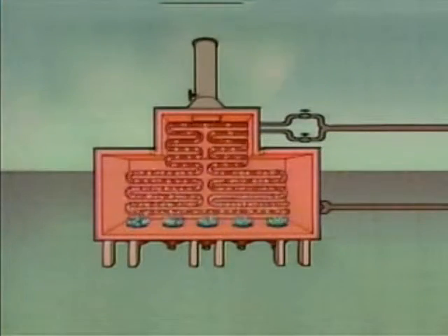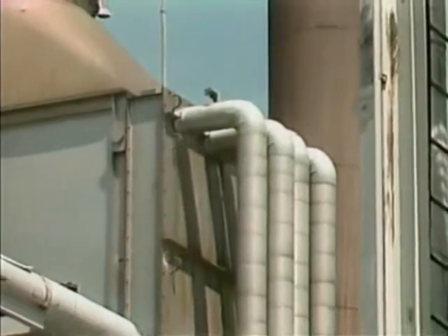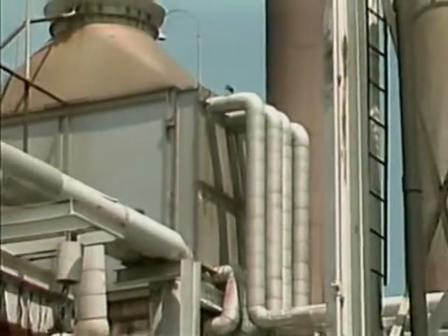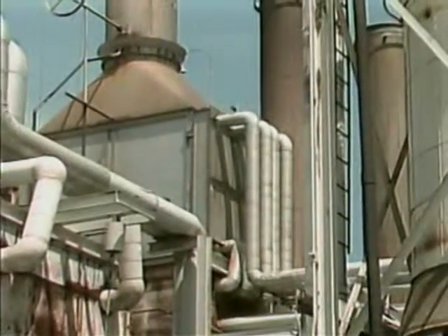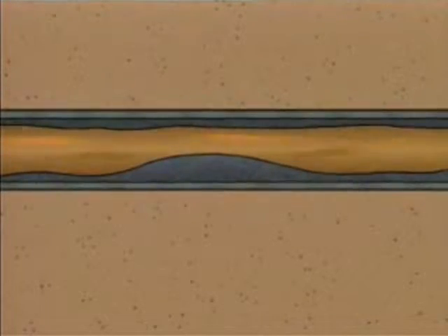In multipass furnaces, the flow of fluid through the tubes can present additional problems. In addition to flowing at the proper rate, the process fluid should move evenly through all of the tubes in the furnace. If the flow is not even in all the tubes, the fluid will not be heated evenly. As a result, the temperature of the fluid leaving the furnace may not be within the specified range. Also, if the process fluid moves too slowly in a furnace, the likelihood of coking and its associated problems could increase.